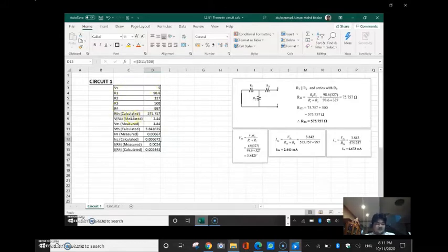Now this experiment will show that from the obtained Thevenin equivalent circuit, the theoretical values will approximate to the matching components. IM will be approximate to ISC, which is the short circuit current. The VM will be approximate to VTH. And by calculating IR4 using the calculated values and comparing it to the measured IR4, this will hereby prove the theory.